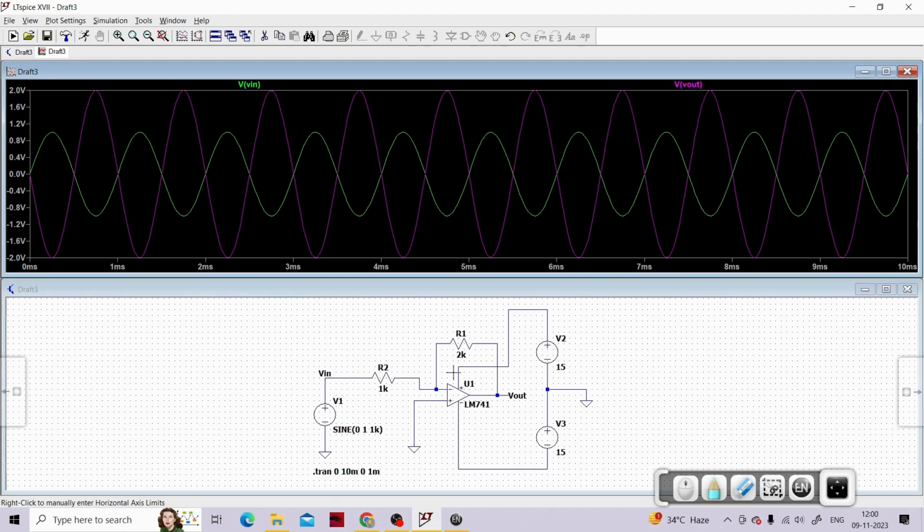We had not connected any compensating resistor over here, and obviously we need to make certain variations in the circuit to get the appropriate gain for higher frequencies. But we had not done anything to this particular circuit, so we just need to check what our frequency response would be. For that purpose, as I had already mentioned, we get the privilege of using the LTSpice software to check everything.